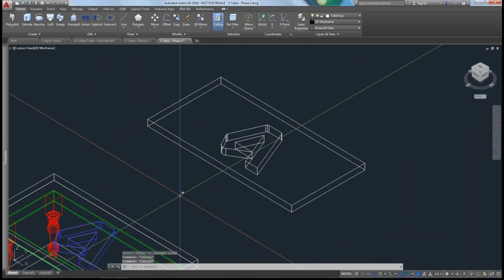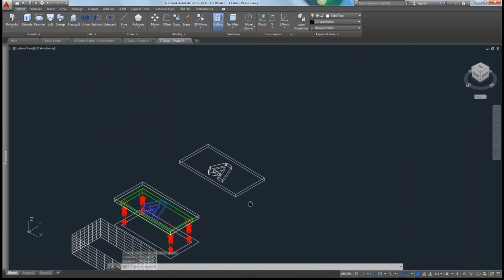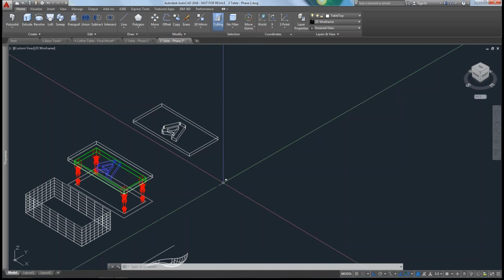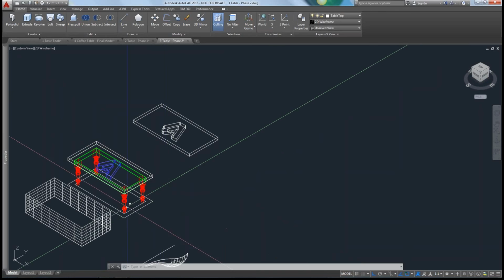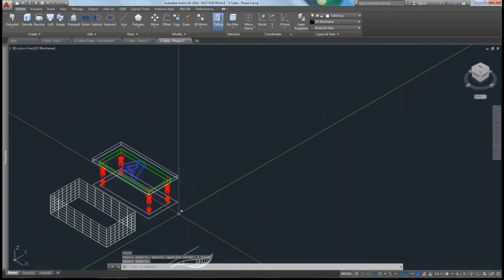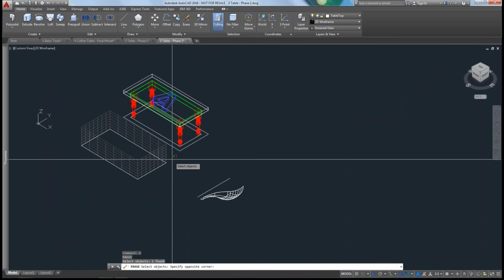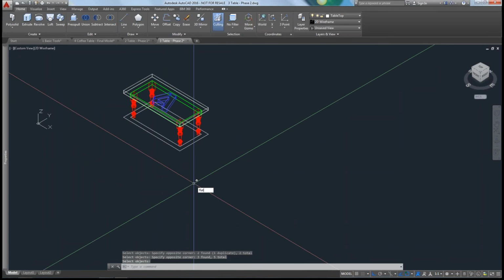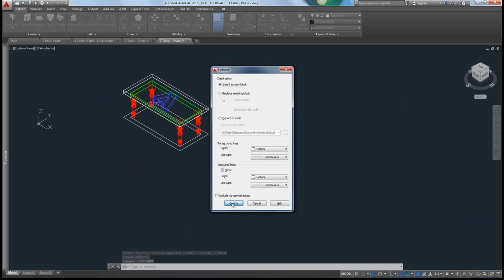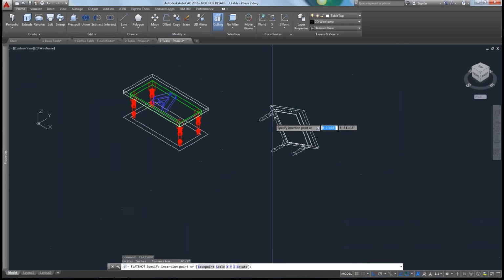Okay. One of the great things. Oh, go ahead. I was going to say, there's another question about how to create a 2D view of the 3D model. So maybe using Flatshot. Yes, actually, we can do that in the model here. Let me erase some of this other geometry I don't need. And using the command, we'll just insert as a new block and create.